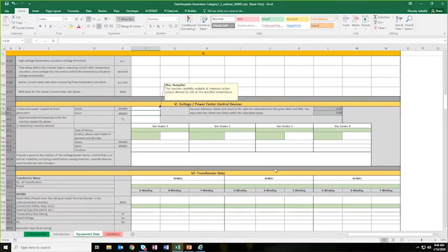Okay, so then where does the Mod 25 verification come into play when you compare that? Because often the Mod 25 test is completed and the machine may not have reached its reactive capability, and may not have fully verified the reactive element that we could potentially put out or take in.